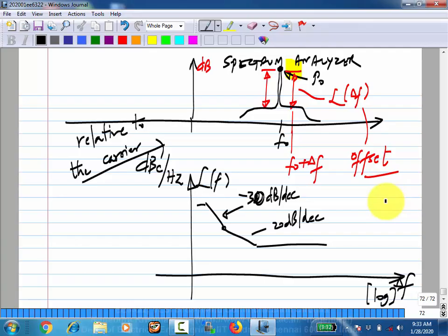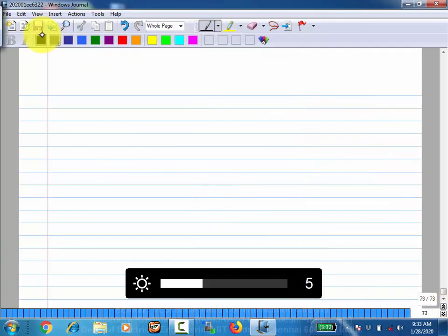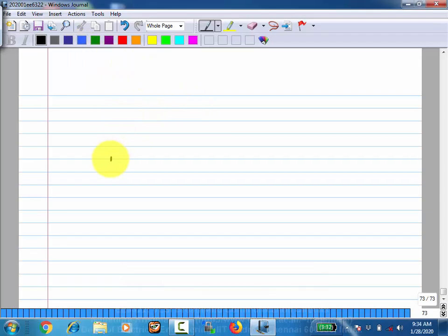That's a very interesting thing you can try. Earlier I said that if you have a circuit, let's say something like this, you have some noise here, let me call it the output noise variance. Now, there may be many ways of reducing noise. One is to invent a new circuit that has less noise or less noise transfer functions and so on. That may or may not be possible. There may not be a more optimal circuit. So without getting into that kind of invention, what is a circuit that will give me, let's say, half of this?